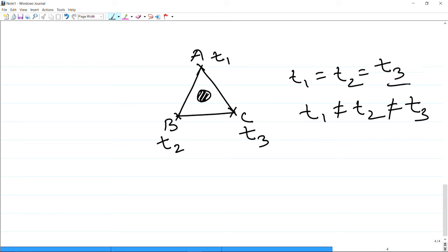So, this is how when you place a number of sensors around particular locations, this will give you an idea based upon these different times that these sensors receive the signal at, and that is how the zonal location technique will indicate the zone or the location from where the acoustic emission signals are coming out.